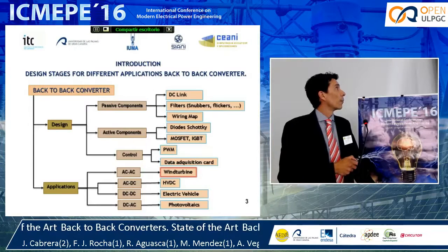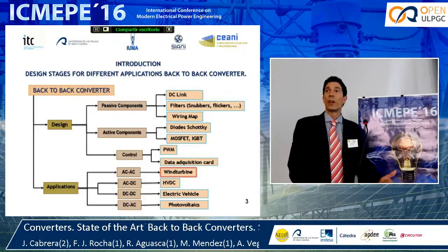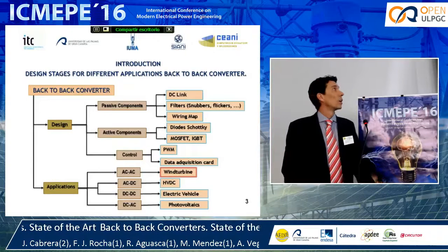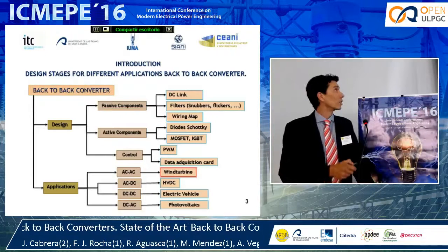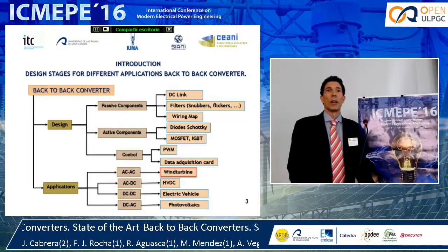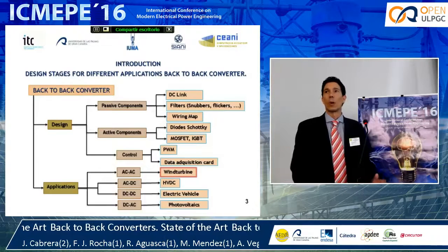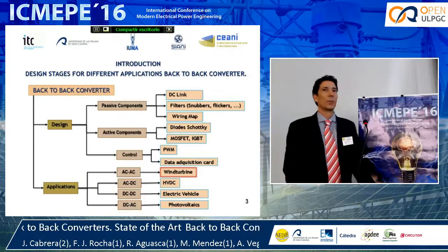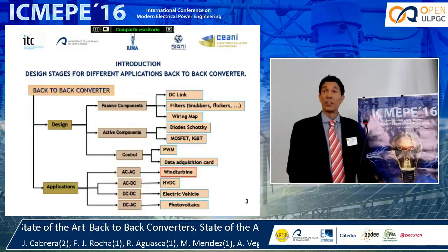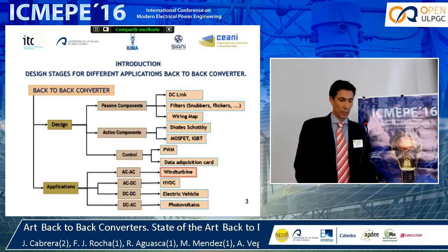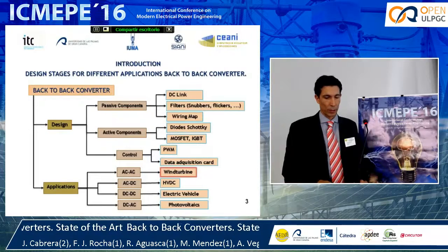Then the selection of the passive components. The generator-side rectifier and the inverter are decoupled, and there is a DC bus link, called the DC link, where a capacitor is installed, which provides some reactive power control and gives some extra power when it's required. Then converter simulation to analyze the signal spectra and ensure the coupling of the different stages of the converter.